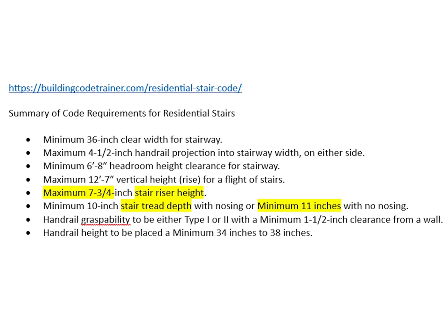Minimum 36-inch clear width for stairway. Maximum 4.5-inch handrail projection into stairway widths on either side. Minimum 6-foot 8-inch headroom height clearance for stairway. Maximum 12-foot 7-inch vertical height rise for a flight of stairs.